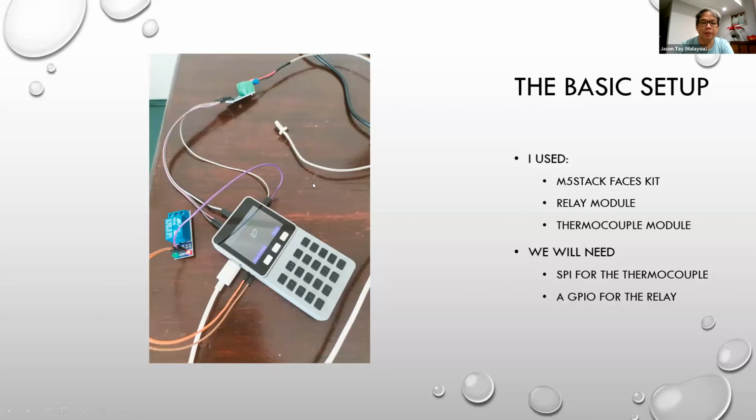So I used an M5 stack and I added on a thermocouple board. The temperatures involved, as you've heard, are not very high. As a result of that, I needed actually to enable SPI. If you notice in the default ESP32Forth source code, strangely, the SPI interface is not exposed as words in the Forth dictionary.